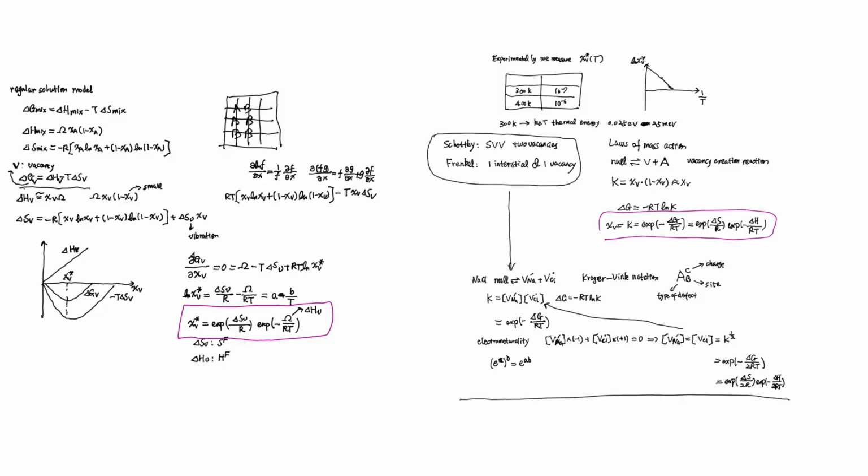So we'll see some numbers, right? Again, we're not going to be limited by this number. We want to use it. We want to think about, okay, that tells us the material is easy to form the vacancy. We have to be careful, because if it's easy to form, then we might have a lot of vacant sites in there that might affect our property, because that implies aluminum is going to be able to diffuse. Once you create vacancies, they can be diffused. And is that a good thing or bad thing?